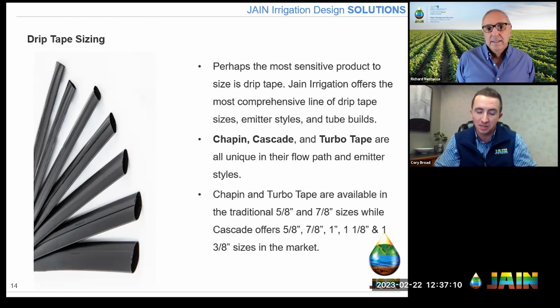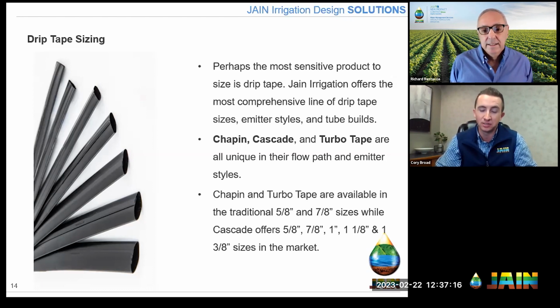So you're a little sensitive maybe. And you sit there and go, okay, well, I don't really know if I need that. But then I say, Richard, you need to have more piping if we go with smaller tubing. I can't cross the field once, I have to cross it twice. And you go, okay. And I said, well, that's twice as much trenching for me. And it's twice as many risers. And then also when you go to flush it, there's twice as many hose ends. And so again, it's about working through that balance with somebody that has that experience to say, here's the pros and cons to each of these decisions.